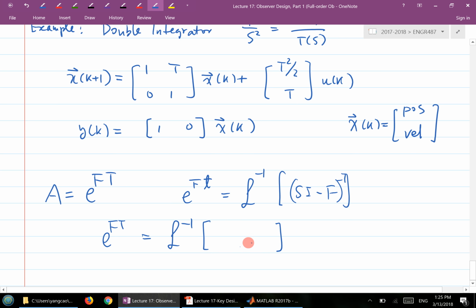When you do the inverse Laplace transform, it's supposed to be a t here, which comes from the inverse Laplace of 1 over s squared. But then you look at your Laplace table, and instead of using t, you said kT, because the small t after sampling is k times capital T. So that's a mistake. Then you basically say A equals this whole chunk, with 1 in here, 1 in here, and kT.